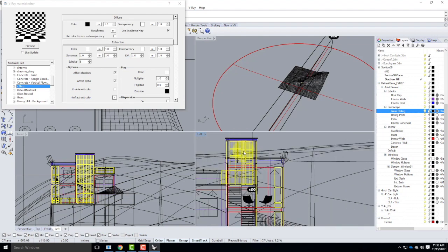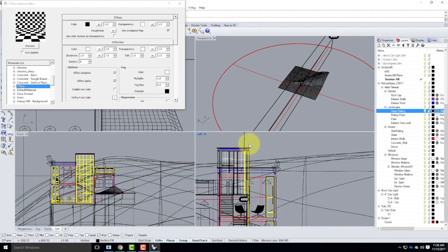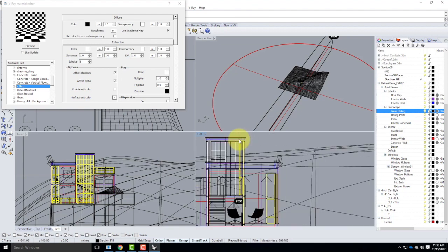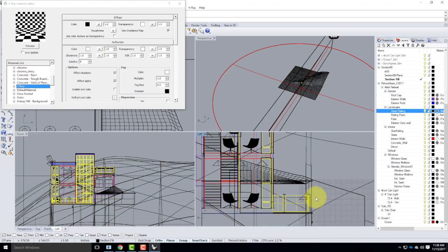The glass needs to perform as normal on the side of the section that I'm keeping, but it needs to go away, or needs to change, on the side of the section that I'm making transparent. So at this point, I need to hold down Control, and I need to deselect all of the glass that's on this side of my section. So we'll zoom in here a little bit, take a look. Yep, looks like all the glass is now on that side.